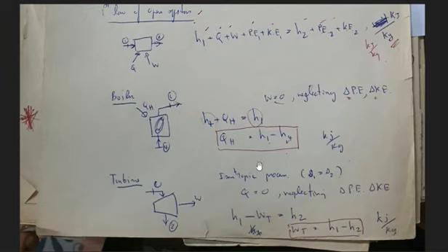So we can neglect the potential energy and kinetic energy, and we get the energy coming into the turbine as H1, and then we have to subtract the work going out to generate the electricity, and we are left with the energy at point 2. So we can determine the work provided by the turbine, Wt, by H1 minus H2.